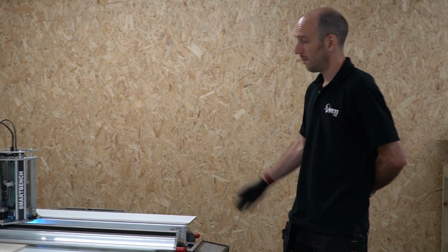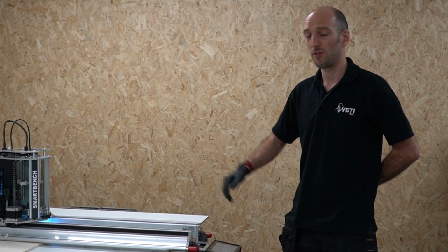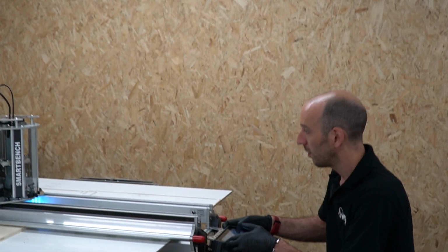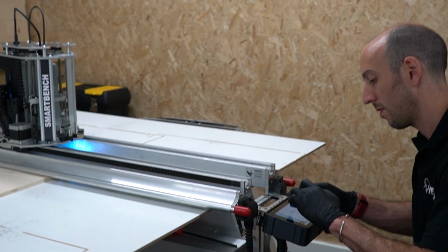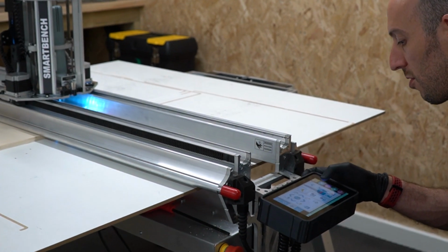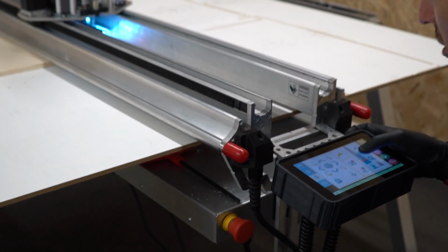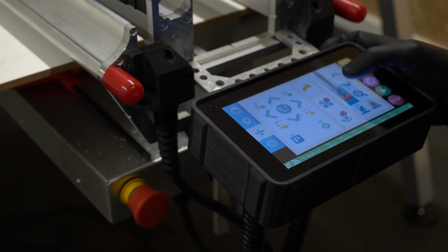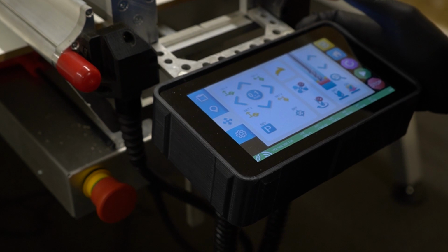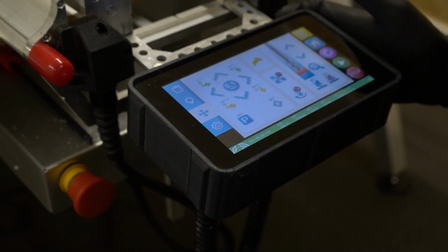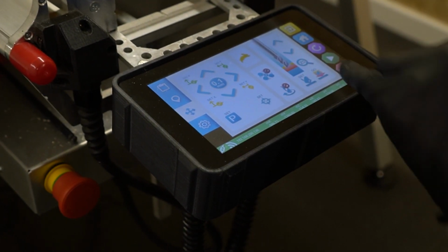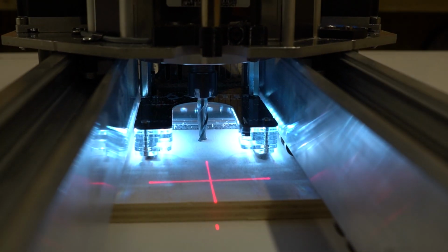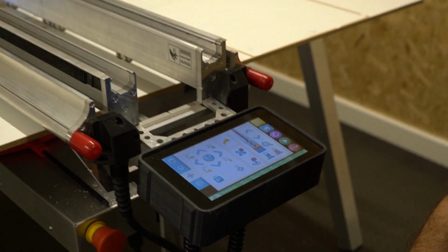Let's do that now. I've moved my Z head over the top surface of the stock material, and now I'm going to lower the tool. As I get closer to the top surface, I'm going to move to 0.1 millimeter increments, and just watch until that tool just kisses the top surface of the material. When I'm happy that's the case, I'll then just push the set button. And that means that SmartBench will have set its working datum to that height.